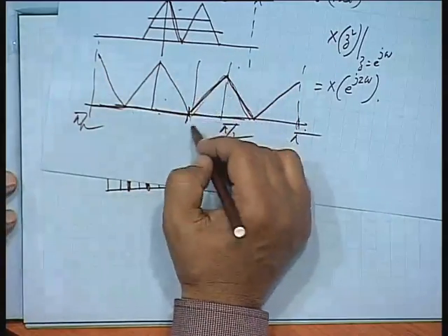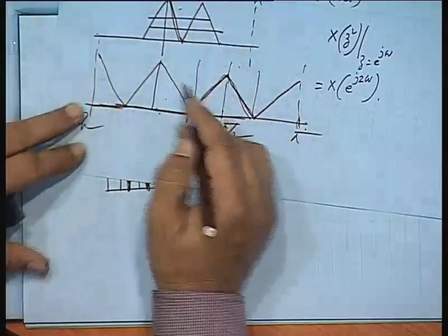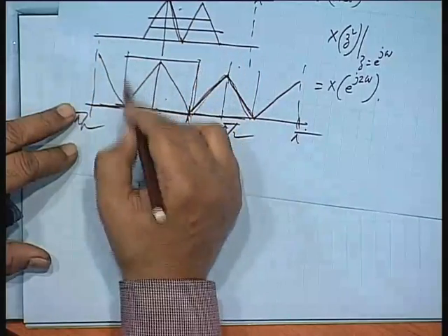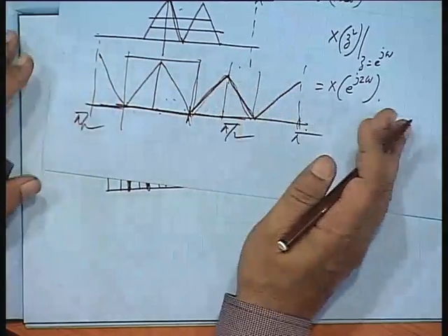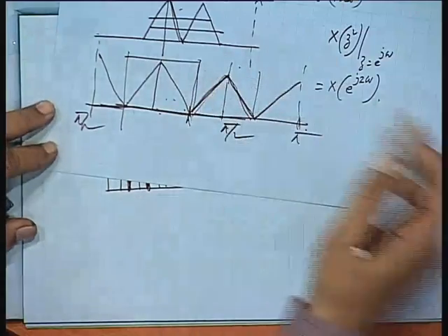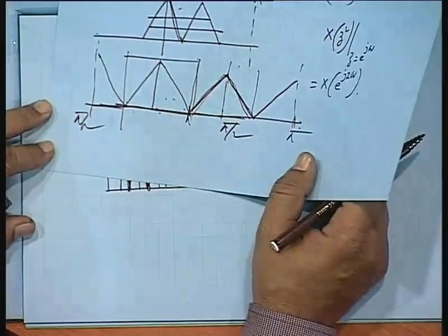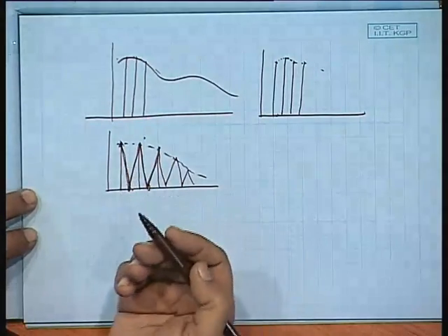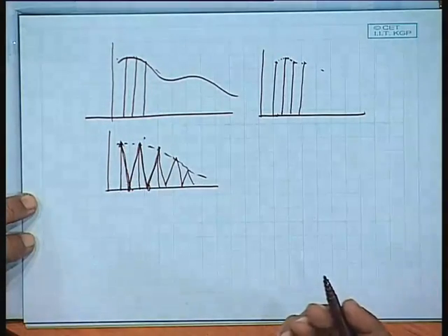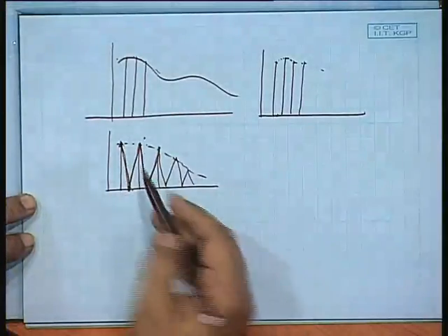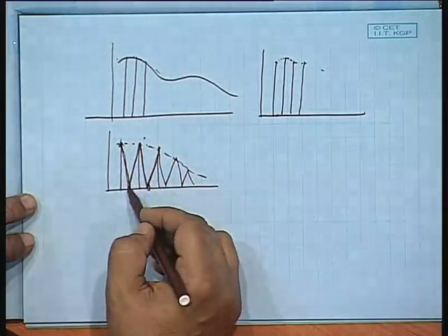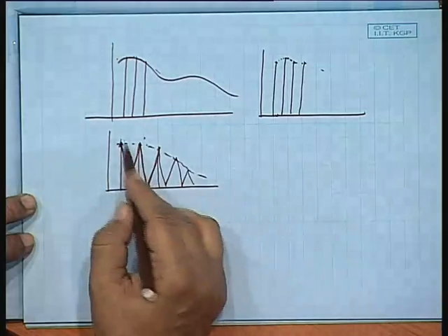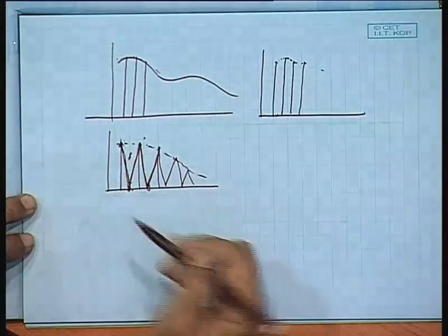So if I have a low pass filter, I will allow only this and drop this, then I can reclaim the original signal. Is that all right? For example, averaging is a low pass filtering. Suppose I take a 3 point average, so this plus 0 divided by 3, then this will be brought up somewhere here.